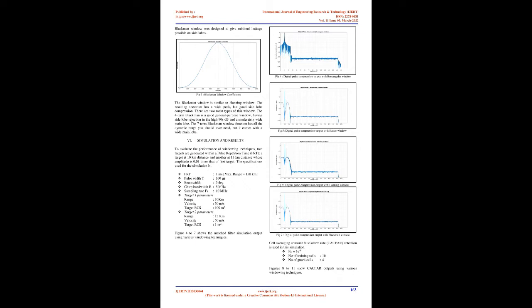4. Windowing functions. There are several different types of windowing functions that can be applied in radar applications depending on the signal. To understand how a given window function affects the frequency spectrum, it is required to understand more about the frequency characteristics of windowing functions. An actual plot of a window shows that the frequency characteristic of a window is a continuous spectrum with a main lobe and several side lobes. The main lobe is centered at each frequency component of the time domain signal, and the side lobes approach zero. The height of the side lobes indicates the effect the windowing function has on frequencies around the main lobes.